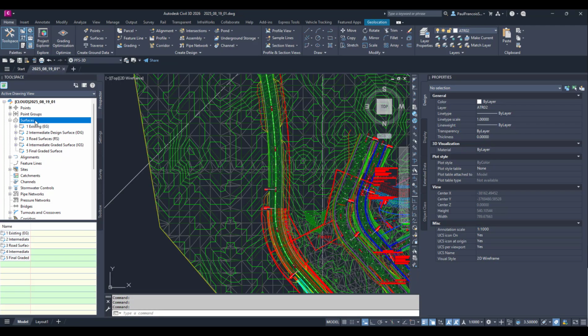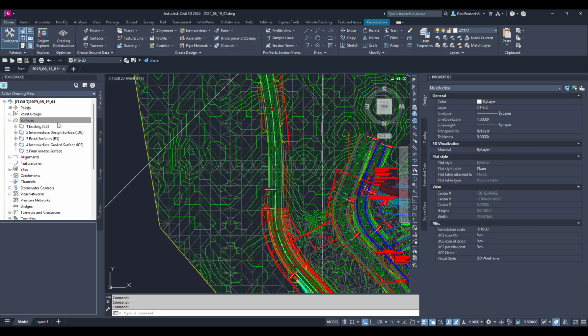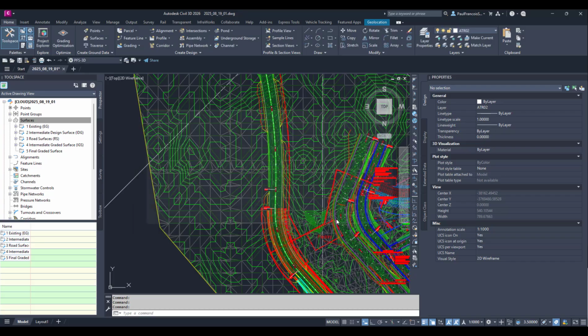Now if you go back to the prospector and we create that surface and just take the default, we'll see that it's blue. That blue means, and now you can see it's a pentagonal shape, and I don't know if your eyes are good enough, but if I hover over that, it should show us there's a little pentagonal shape, and it's only got 3 triangles. It's only got 3 triangles. So in other words, it is a reduced level of surface.